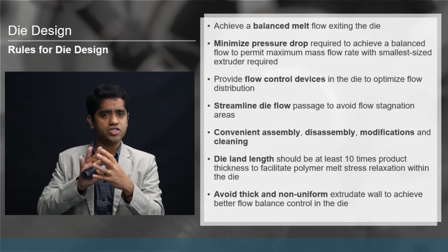because it builds a lot of stresses in the barrel. If you think about the barrel, you have a uniform gap in the feed zone, then it's compressed in the transition zone, and then again you have a uniform gap in the metering zone.